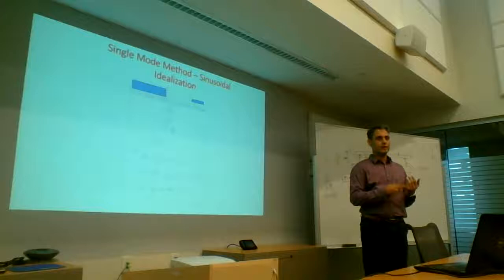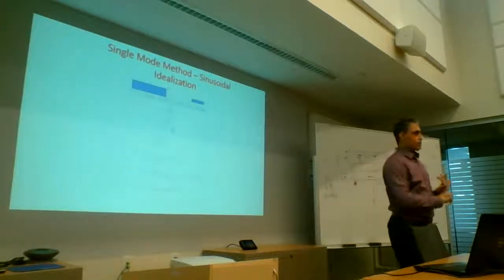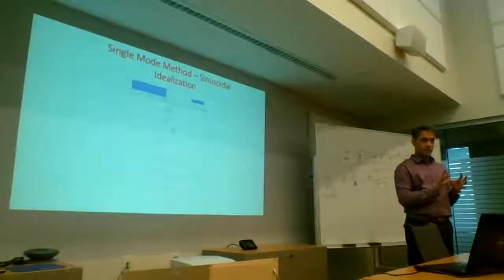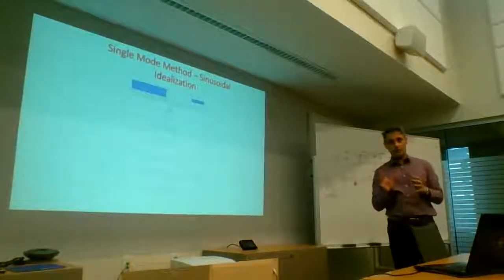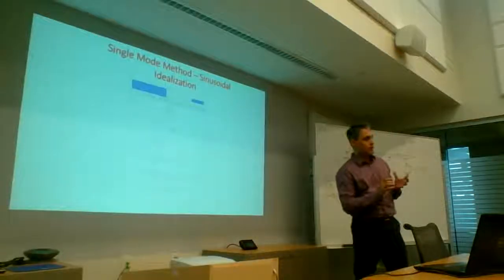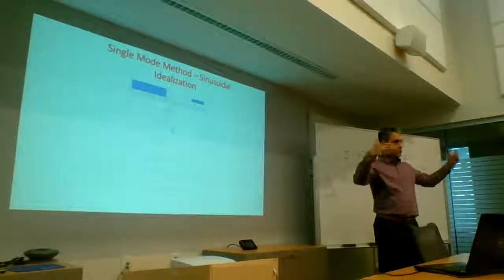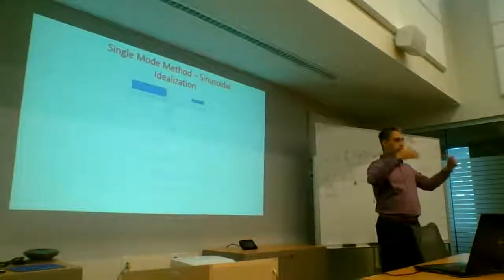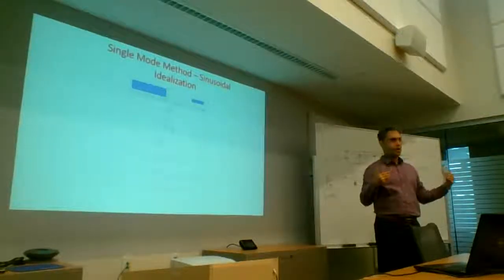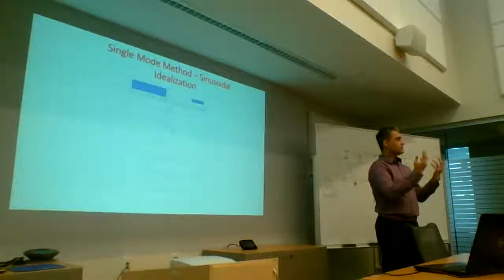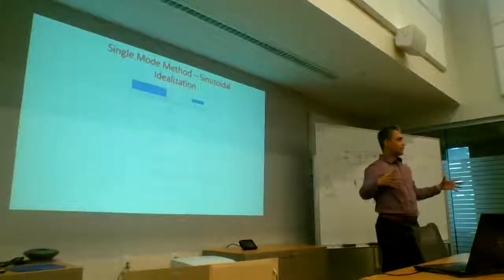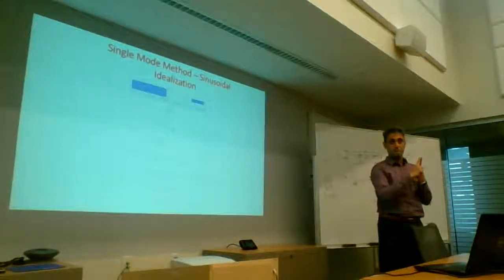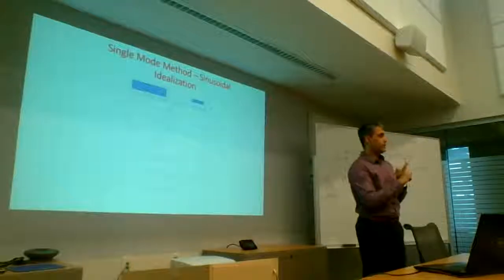The things you should be looking for are the following. To check that you haven't made a mistake in your input and that the software isn't doing something kooky, have a look at your total bridge deck mass. Run your gravity analysis in your model. Check that the total reactions are equal to the total deck mass plus whatever little bit the columns have. That should always be your first check. Have I accounted for all the dead load?